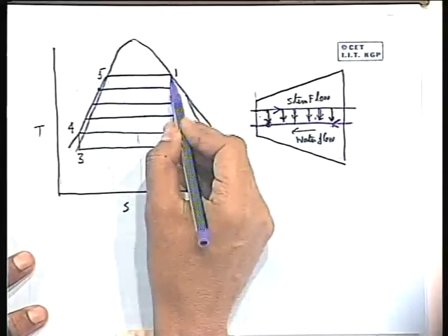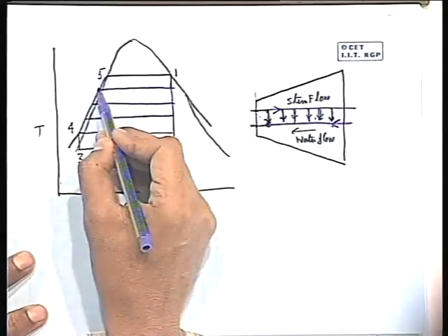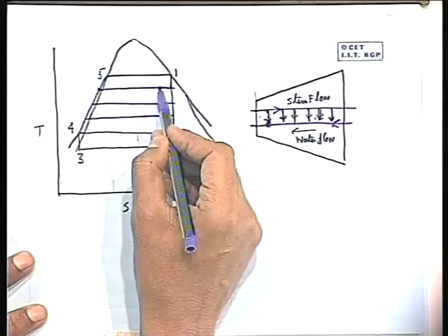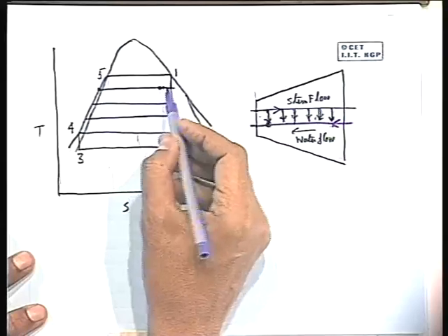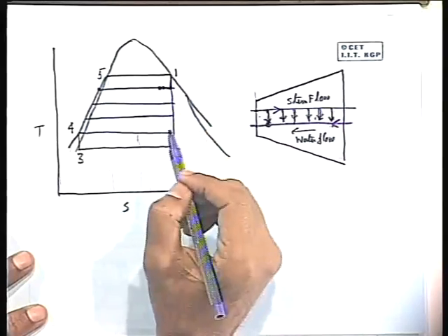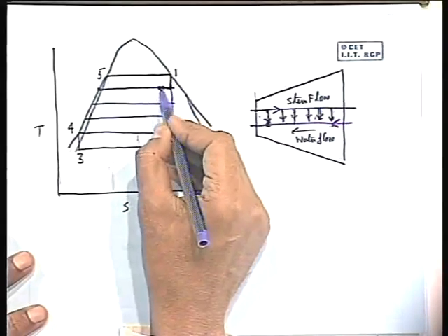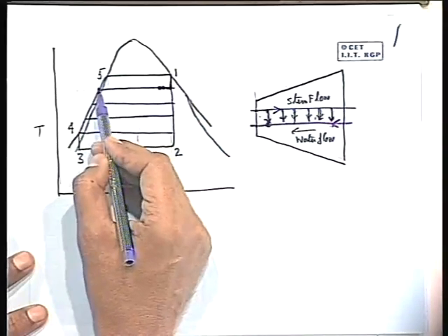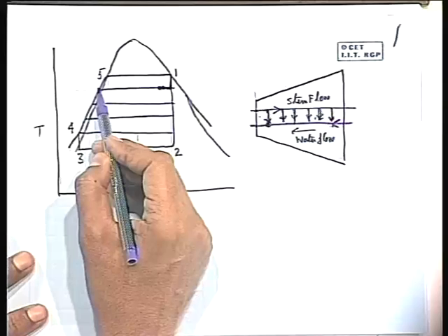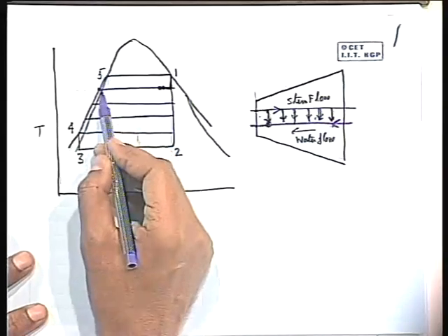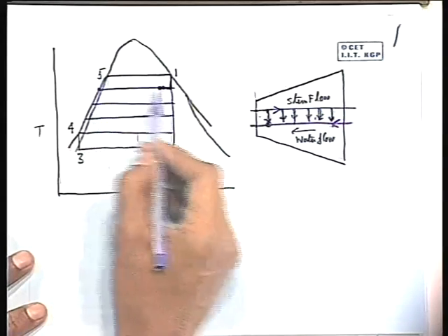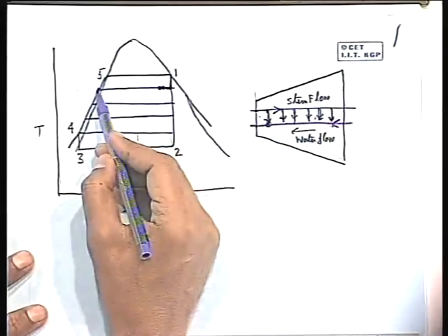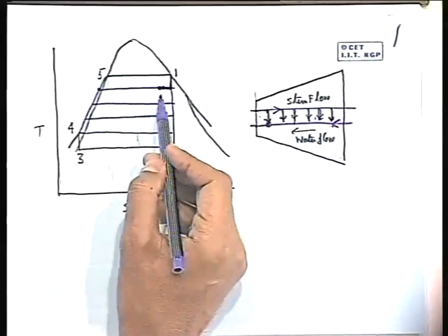So if the steam has to give heat to this water to be heated, then the steam will be condensed. Try to understand, steam will be condensed here at some position. That means steam is condensed like this. Therefore, steam here will be condensed to some extent at that temperature, where water at that temperature will take the heat and raise its temperature. So during the heat transfer, water temperature will rise. You can ask me that a temperature difference will be there, but this temperature difference is so small that if you consider infinitely small divisions, there will always be a delta T temperature difference for the heat